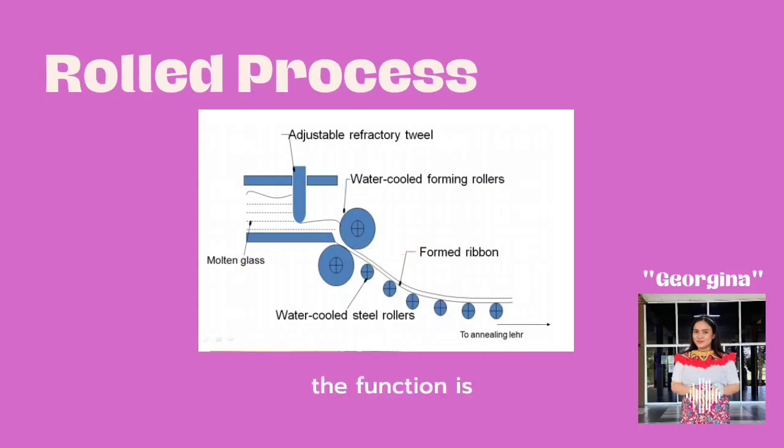The rollers are water cooled to extract heat from the glass. Water cooling helps fix the pattern on the glass and prevents it from sticking to the rollers.